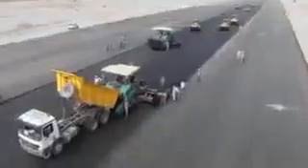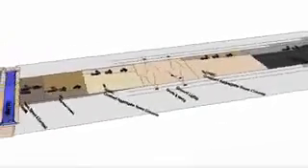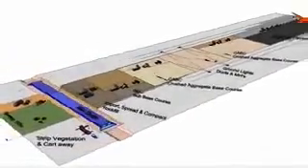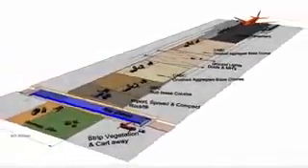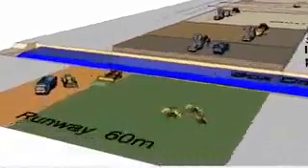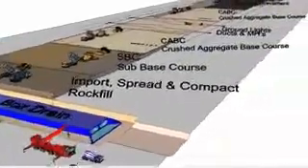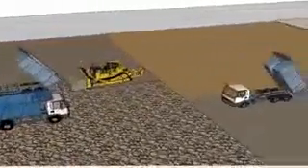Airport runways. The asphalt mixture is laid with 2-tracked pavers, equipped with extending screeds, tamper, vibrators, auger, and conveyor. The pavers work in echelon, in a staggered formation, producing a 15-meter wide mat.